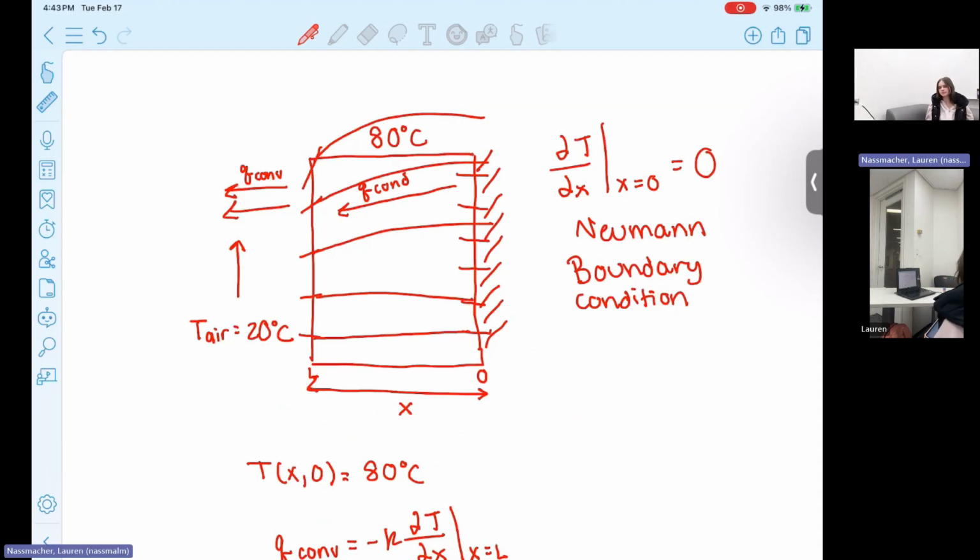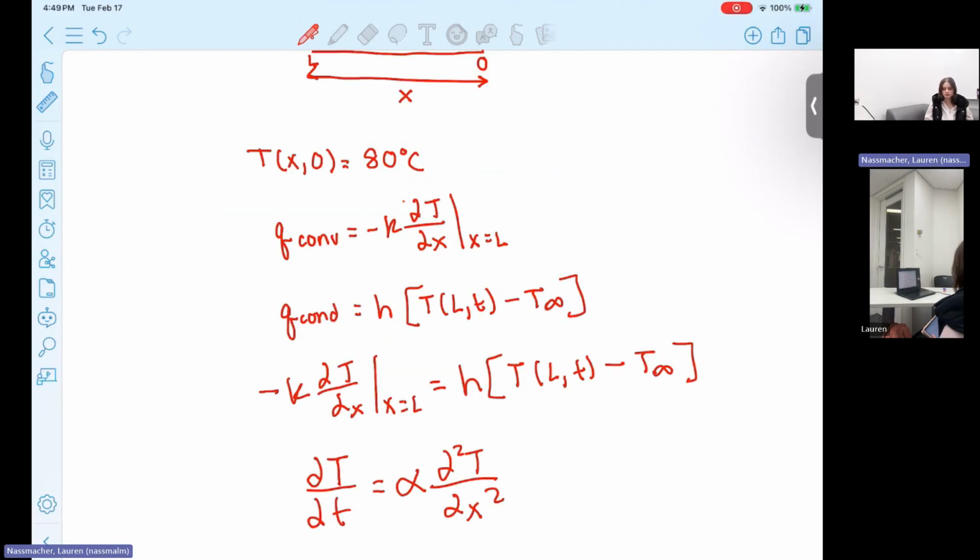As time progresses, the profile becomes more nonlinear, and eventually it will reach a steady state shape. This is because the heat conduction through the slab and heat convection from the slab to the surface will slowly balance. If the convection coefficient is high, you will find that the steady state profile will become a linear temperature gradient.